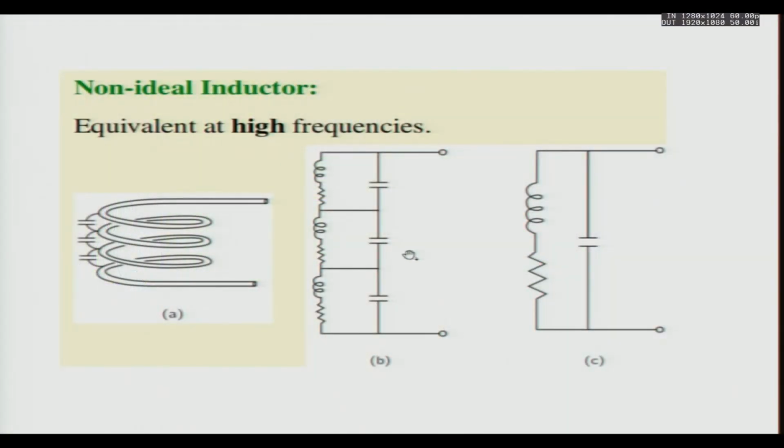In a real life situation, if you take an inductor or a mutually coupled device like a transformer, and because of some reason the geometry of the coils changes, you will find that the capacitance and the inductances of this circuit will change. For example, if you look at the distributed parameter model of an inductor, these capacitances are dependent on the geometry of these coils.